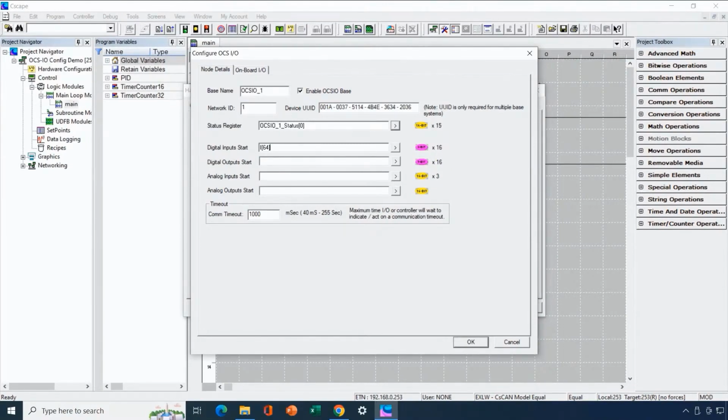Because we're using variable-based advanced ladder, we need to reference one of the variables built into the project. By default, there are some real-world I/O arrays we can use here. So we're going to use I64 because arrays are always 0-based. So %I65 references I64. Always the index is one less than the actual 1-based memory address. So we'll fill in the rest of these, and we need to make sure to put them in a location where they won't conflict with the built-in I/O.